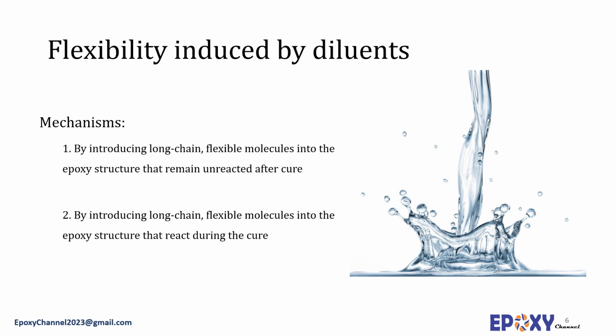The reactive diluents are generally preferred for structural applications because they do not degrade end properties as much as unreactive diluents do. Moreover, the flexibility resulting from diluents is not comparable with the flexibility resulting from synthetic elastomers. They provide a degree of resiliency to normally rigid systems, thereby improving properties such as impact strength and thermal shock. In adhesive systems, they relieve internal stresses and provide a degree of resiliency that is better suited for counteracting different thermal expansion rates between the adhesive and the substrate, and they also reduce the amount of stress caused by shrinkage during cure.